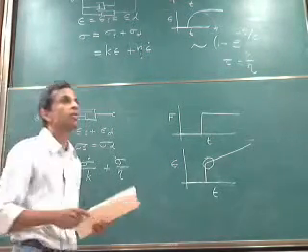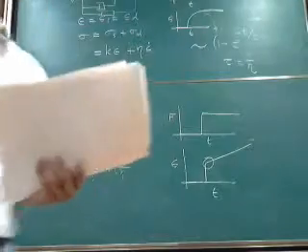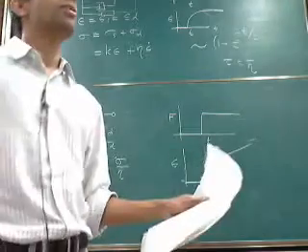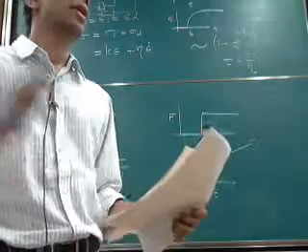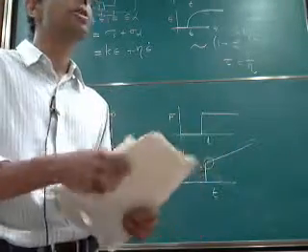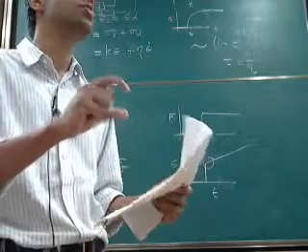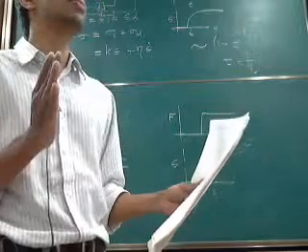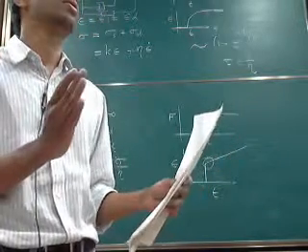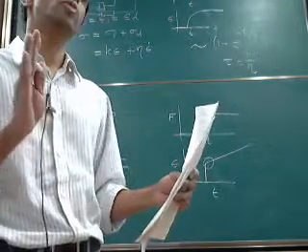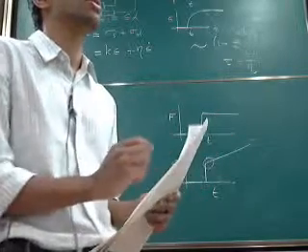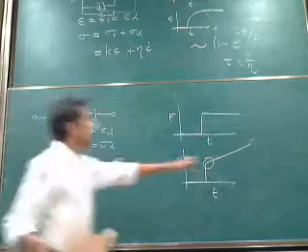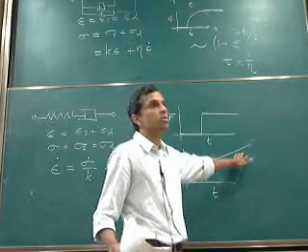How does it happen that even with a small force it will go on extending? Because this is like a syringe and a piston. If I take a syringe, fill it with water, and press on the piston, if the friction from the piston is not too high and it's just the liquid which is contributing, irrespective of how small a force I am applying, the piston will keep moving. If the force is constant, it will move with a constant velocity. That is the reason why here you get this slope.